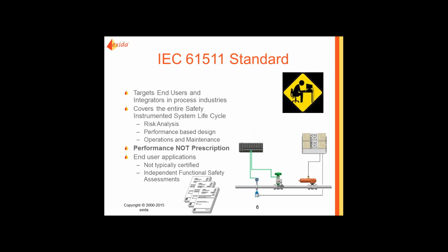We talk about the analysis phase, where we look at the risks, we look at the hazards from the process side, and we look at what layers of protection we have in place and how much additional risk reduction we need, and therefore what is the requirement for the safety instrumented functions that would be in our safety instrumented systems from a performance point of view.